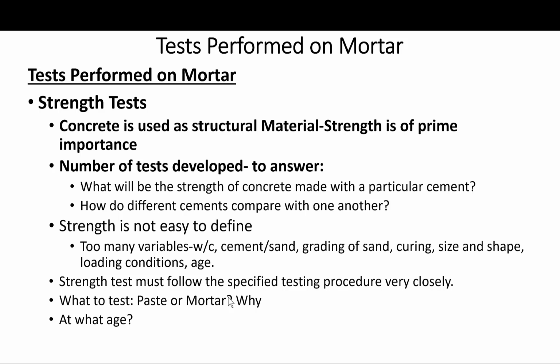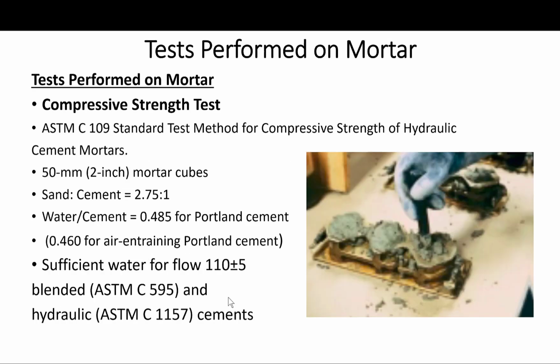The strength can be measured in compression, tension, and flexure. So we will look at the compressive strength and the flexure. Okay, like I said, the compressive strength test is by far the most common measure of strength required by cement specifications.